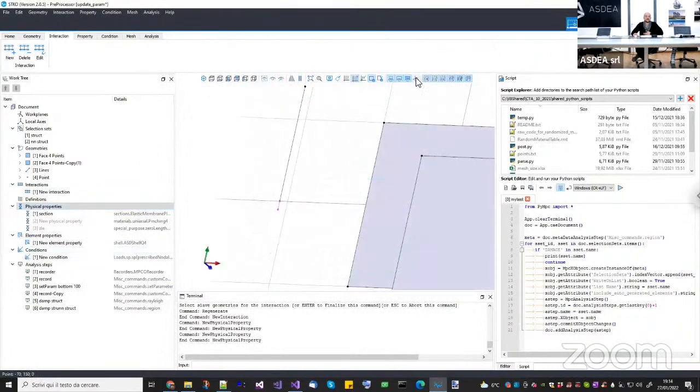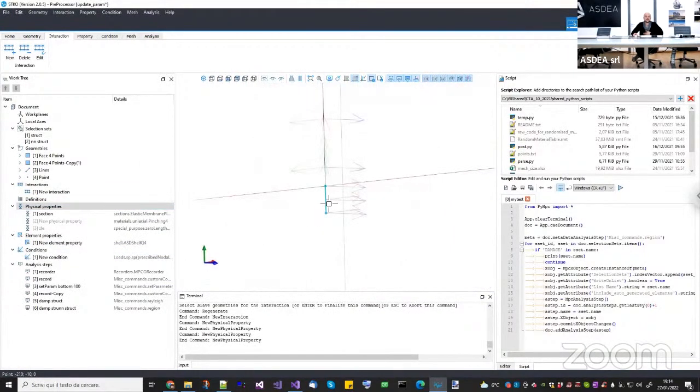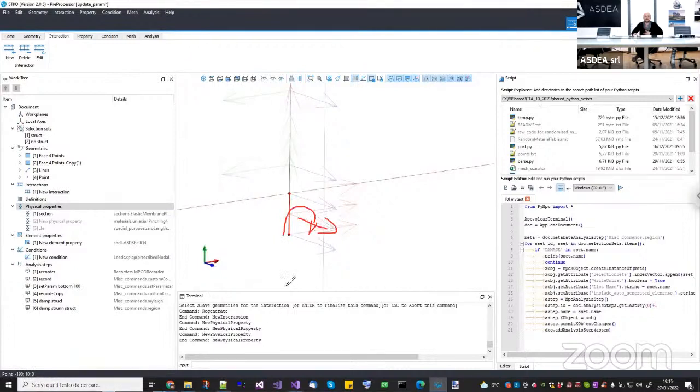Let's switch on the local axis, and you can see that this element has the global local axis now. For example, in your case, you want to check the rotation about, I don't know, about here, for example. Rotation like this. So it will be the rotation about this axis, which is the Z1. The blue is the Z1, the X is the X, and the green here is the Y. So you have X, Y, and Z in this case for the zero length. So you want the rotation about the Z axis, so it's the rotation about the sixth degree of freedom.